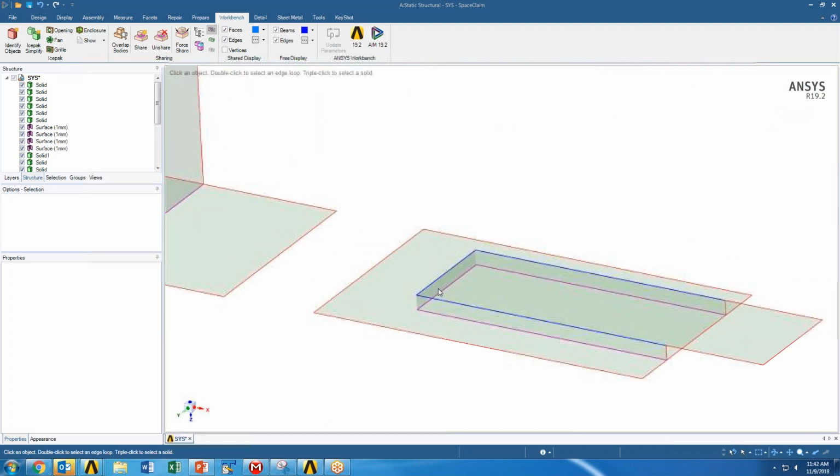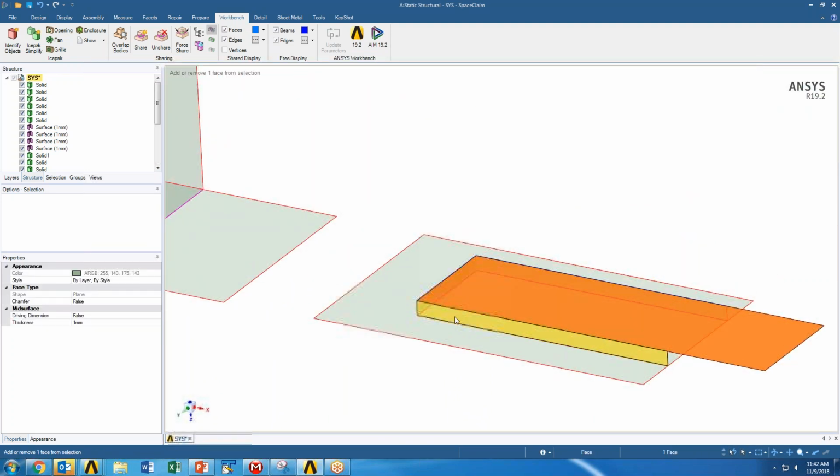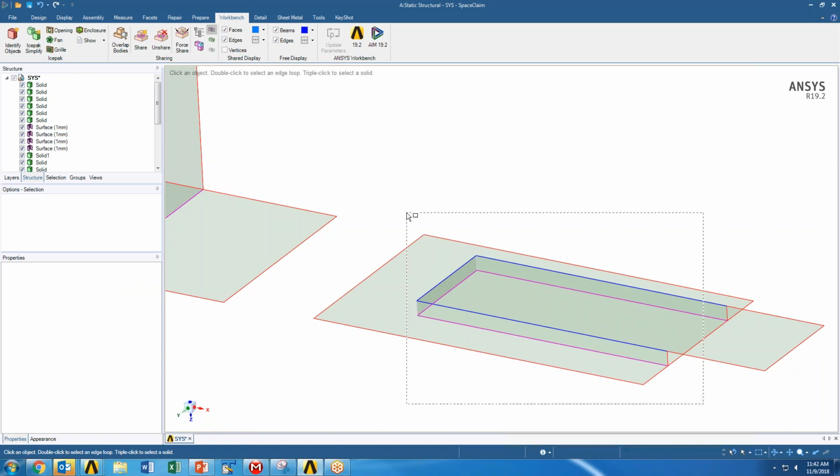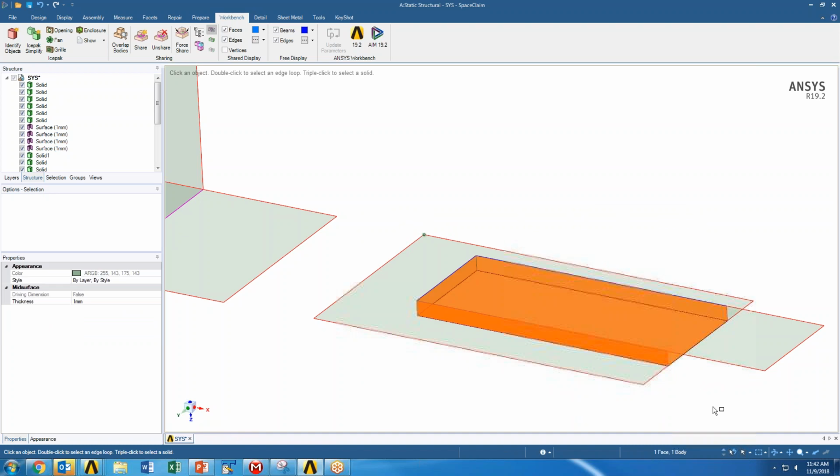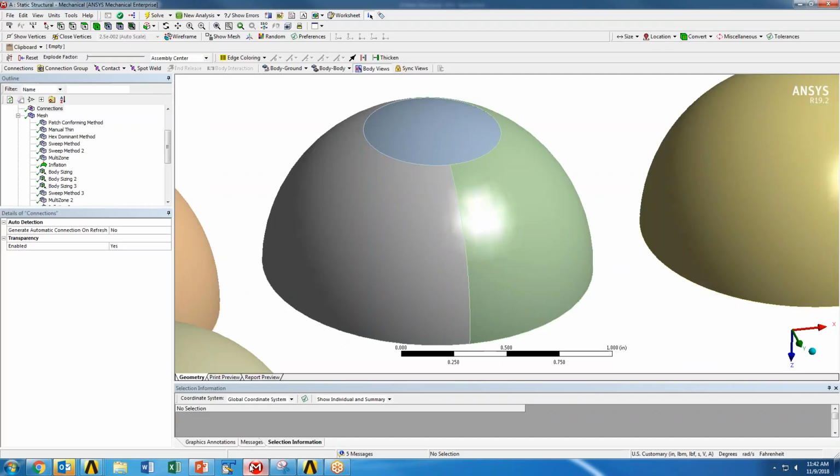And so I've had simulations with thousands of parts and thousands of welds, where at the end of the day I might have 10 different contacts, primarily because I've very much leveraged the shared topology capability. So I honestly cannot stress enough the value of this tool. If you have not used it, play with it, and you will see tremendous value and efficiency increases.